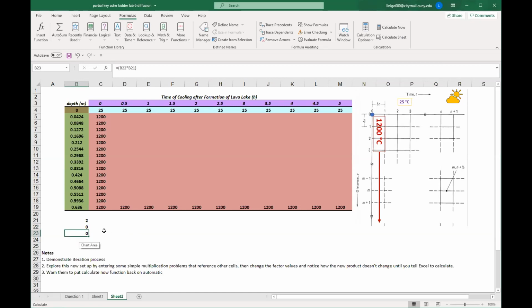Okay. Now, you're gonna have to click this many times because we only did one iteration at a time. And here you have, I don't know how many, like a bunch of cells. So if you do it fast enough, it's cool because it looks like a wave. Anyways, so I demonstrated the iteration process. Oh, and once you're done with this table, make sure that you go here to calculation options and you put it back on automatic. Otherwise, your Excel is not going to actually do the calculations you want it to do.